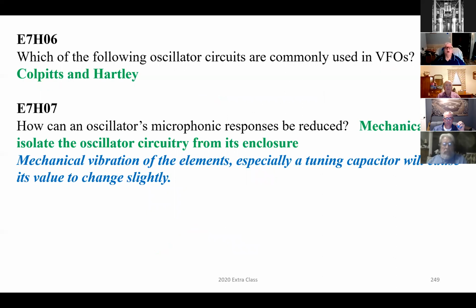Okay, which of the following oscillator circuits are commonly used in VFOs? Colpitts and Hartley. How can an oscillator's microphonic responses be reduced? Mechanically isolate the oscillator circuitry from its enclosure. Mechanical vibration of the elements, especially a tuning capacitor, will result in its value changing slightly.